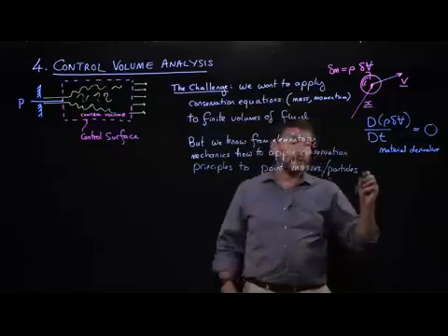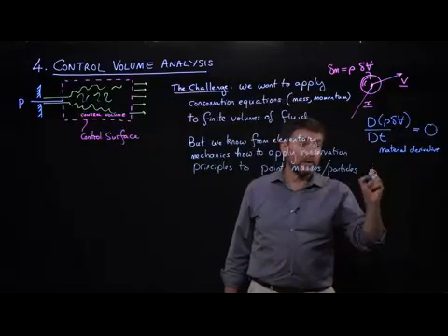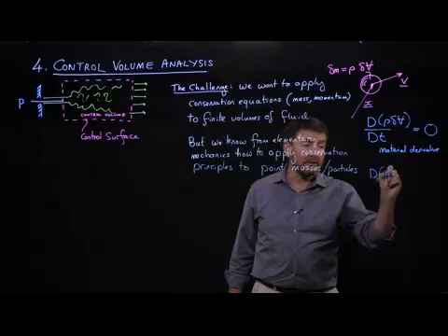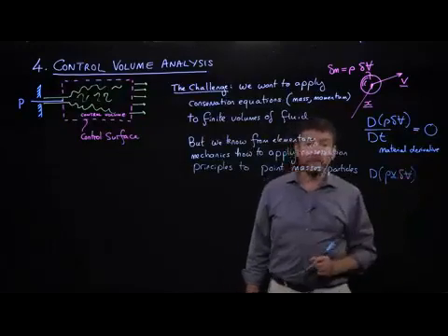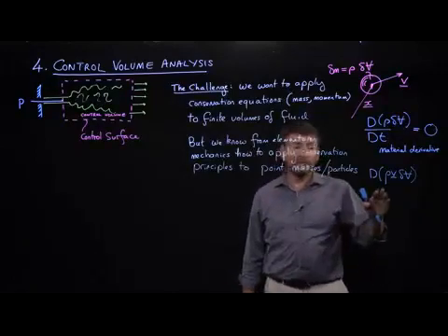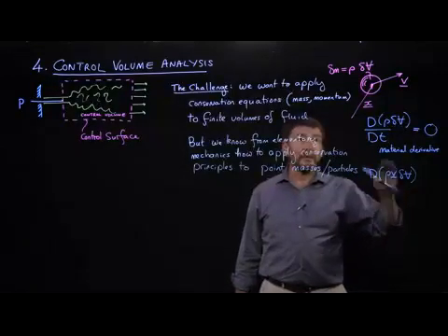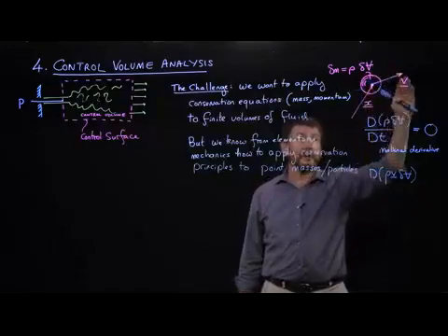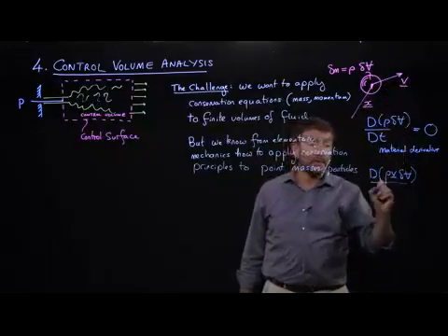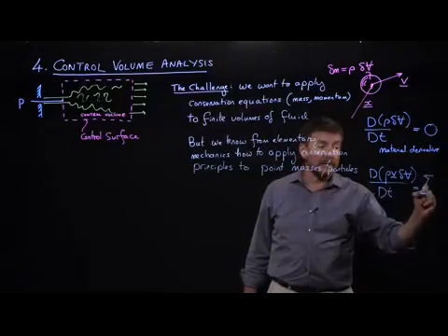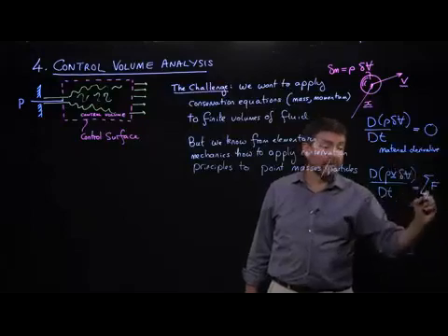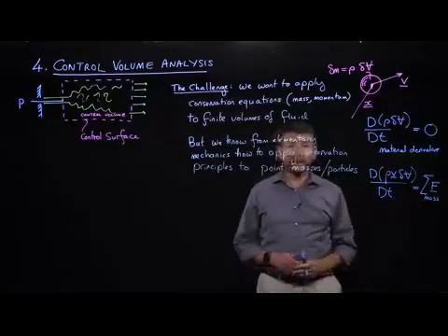Of course, we may also be interested in more complicated conservation equations. So, for example, we might be interested in thinking about a conservation equation for the time rate of change of momentum of our little material mass. So it's rho times the volume times the velocity. And the time rate of change of that, we know how to apply, is equal to the sum of the forces that are acting on our mass, m. So that's a conservation equation that we know.